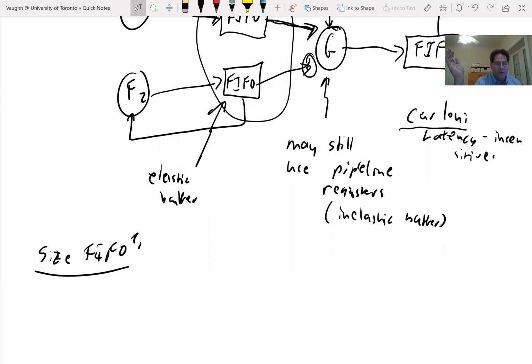We're going to see later in the course that in an FPGA all the RAM's prefabricated. So you actually have certain discrete sizes of FIFOs that are equally good. So in an FPGA, sometimes you size the FIFOs pretty generously because once you're using a certain kind of RAM, you may as well use all of that kind of RAM because you're using the whole block anyway.